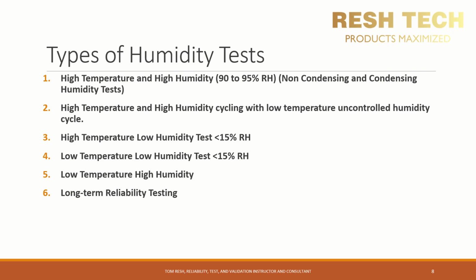You can apply your knowledge or assumption on the field life and temperature humidity environment using the Arrhenius-Peck model to produce and come up with an acceleration factor. However, you need to be careful when creating an accelerated test, and we will go over this in a future video on acceleration factors and their application for reliability testing.